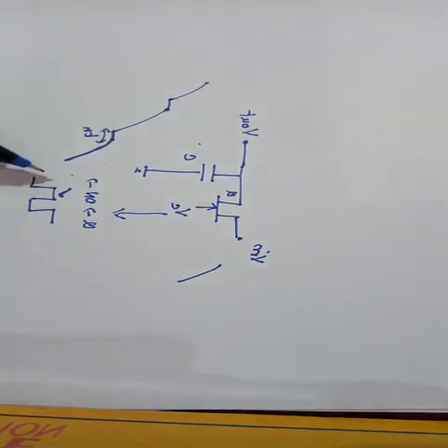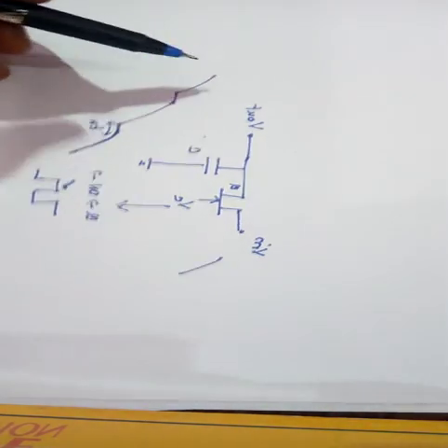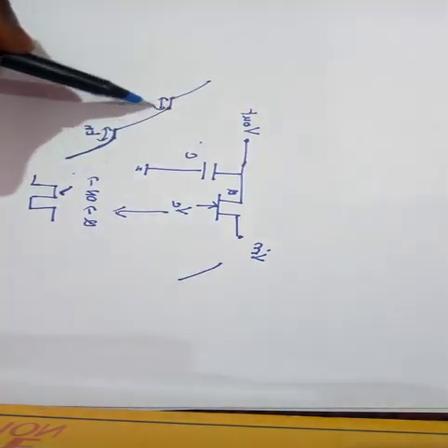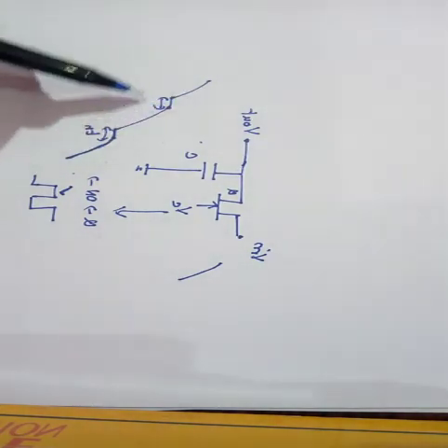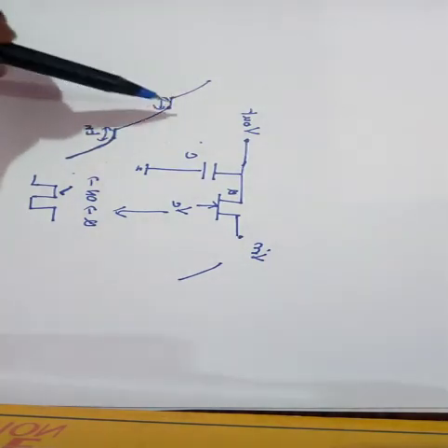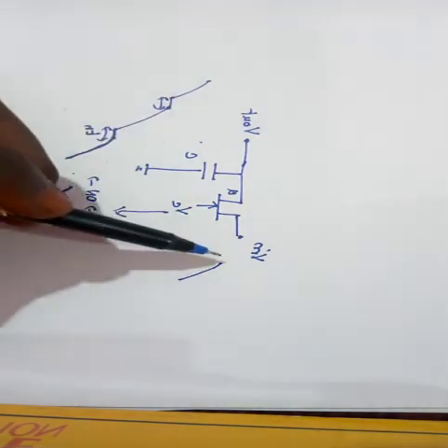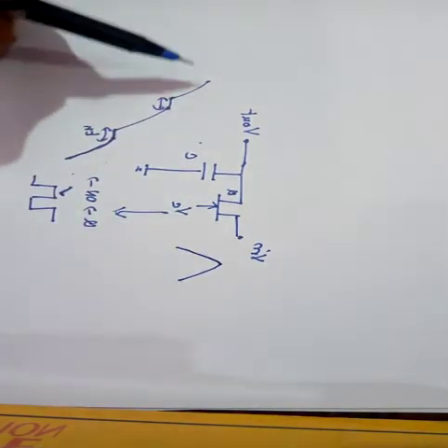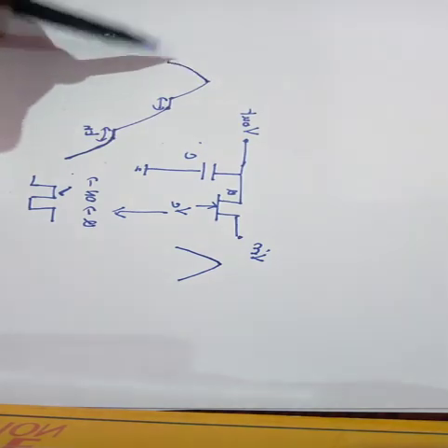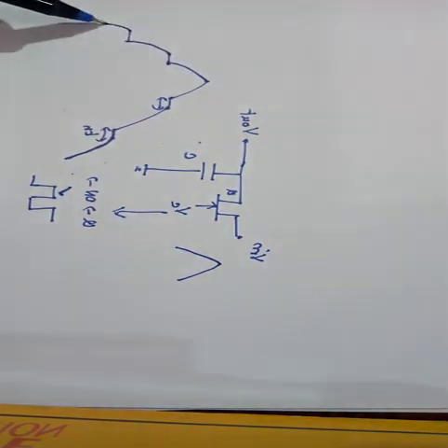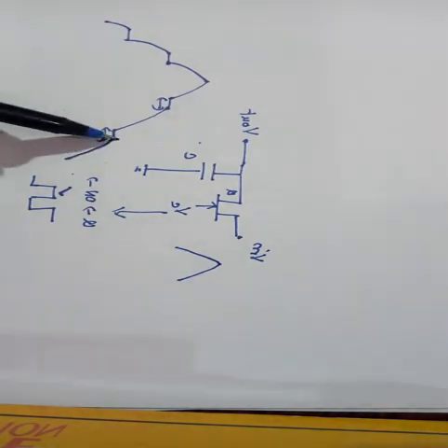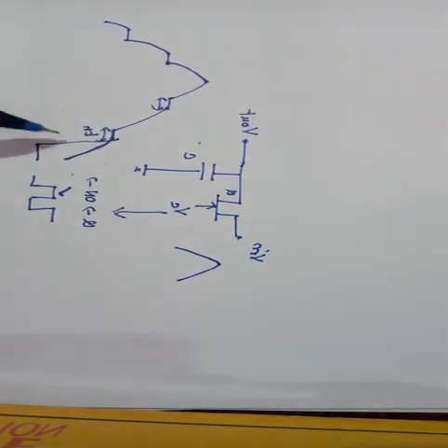Up to the peak, it keeps on charging and holding, because the capacitor cannot find a discharge path for itself. Once the signal goes negative, the same repeats: discharge, hold, discharge, hold. This is the square pulse response.